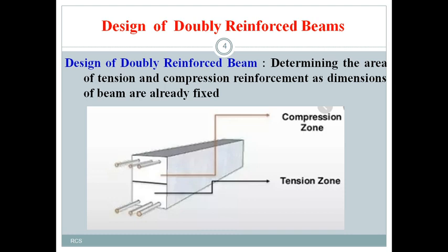In the flexural check, we check the minimum area of reinforcement provided and the maximum area of reinforcement provided, as per the Codal provision. Then we go for a deflection check by calculating the basic value into a modification factor. Same thing we did in our singly reinforced beam, we'll do here. The steps followed for design of shear reinforcement for a singly reinforced beam, the same steps will be followed for this also.